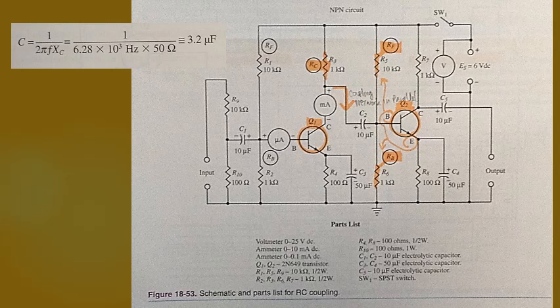With the RC coupling, the loss of power gain caused by the mismatch must be accepted. When cost is a factor, it may be cheaper to add another transistor stage. This addition will offset the loss due to the mismatch and is less costly than purchasing a transformer for interstage matching.